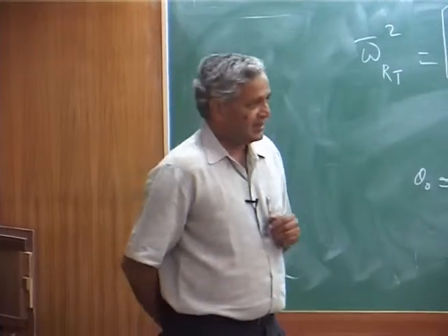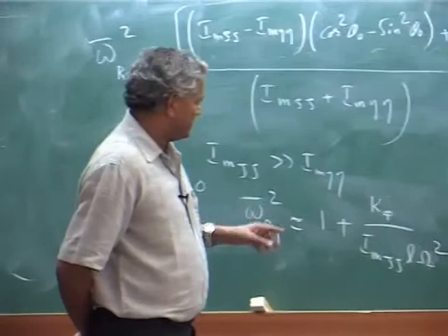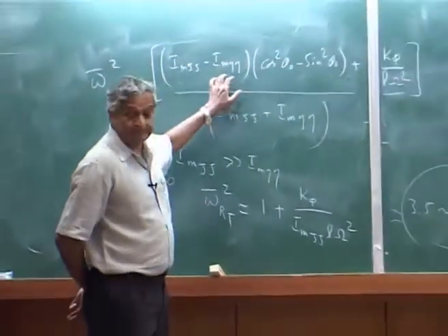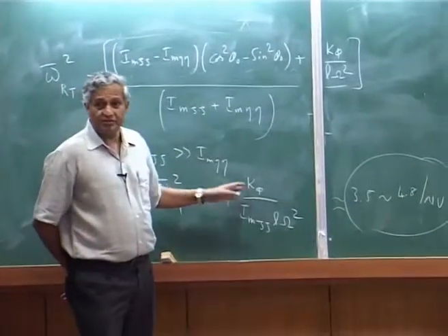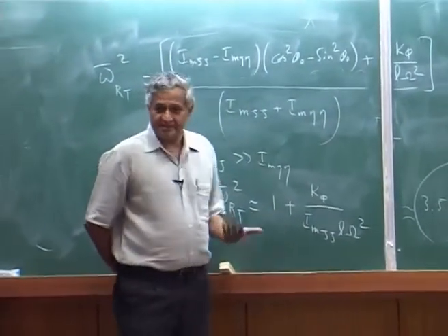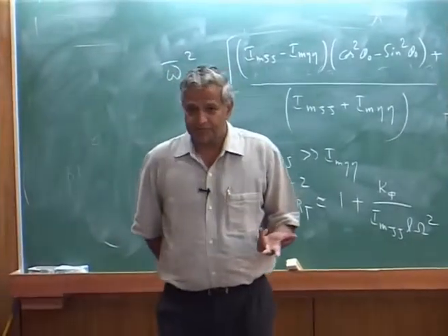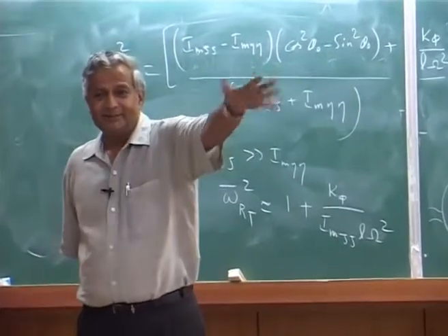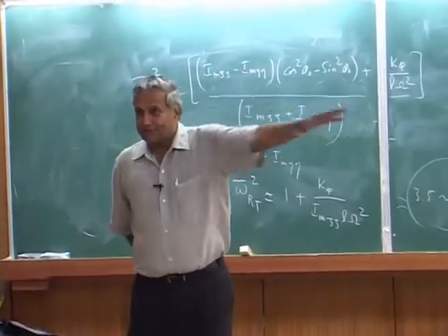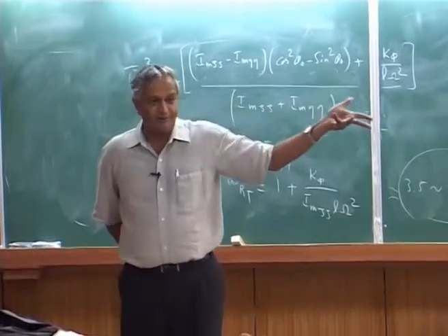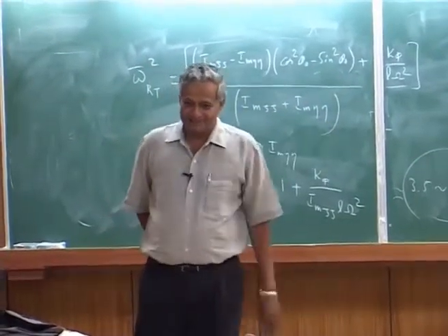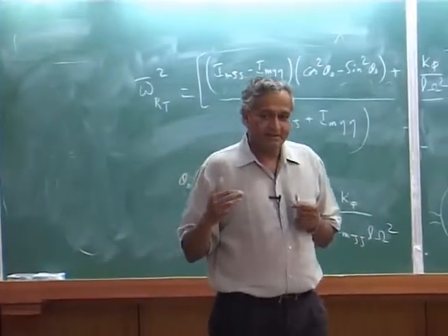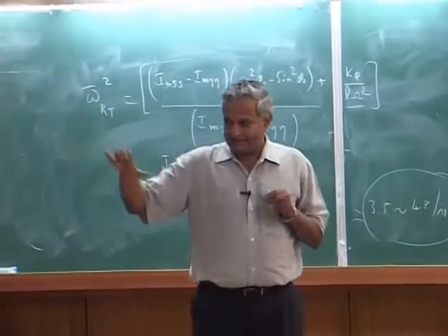Because you have to get some estimate of the torsion stiffness. Okay. And I will not go into the details of this particular term, when I wrote the tennis racket effect, that is basically this. So even if Kφ is 0, that is 1. It's like a centrally hinged flap. So torsion also will oscillate like this if you disturb it, as it goes around, once per revolution. That's all. Okay? It's like a plate. See, that is why when you analyze torsion, it is not a line. It is actually a 2D.